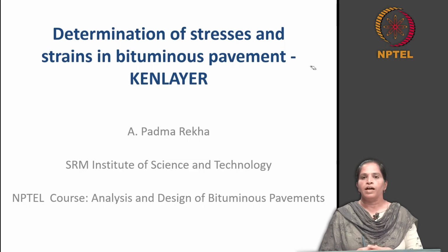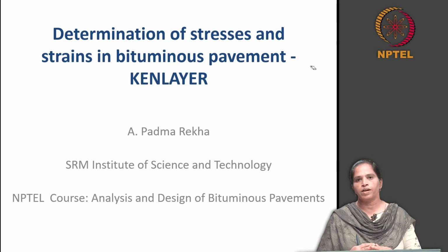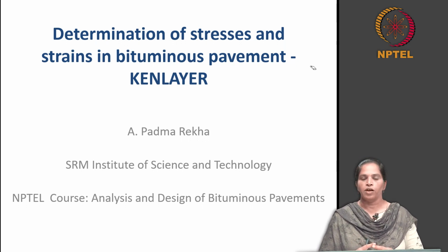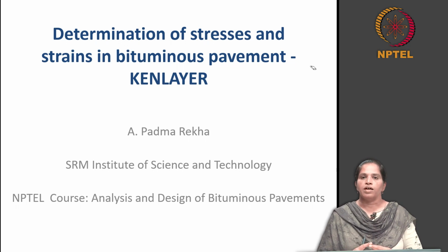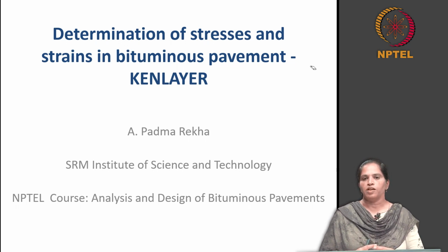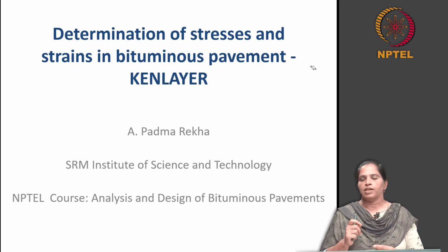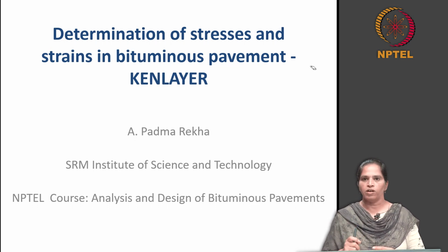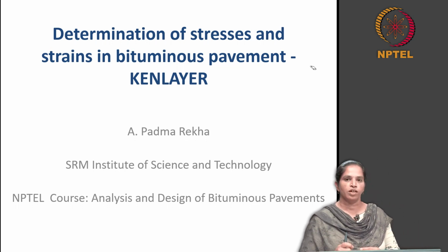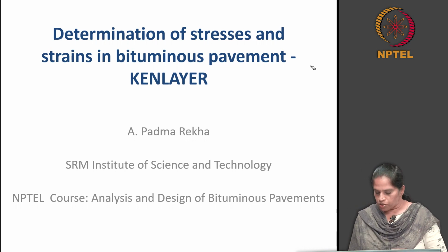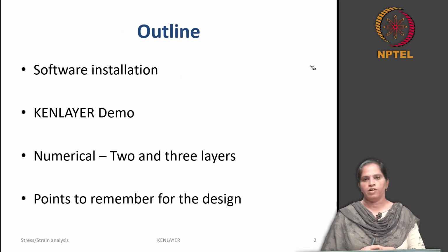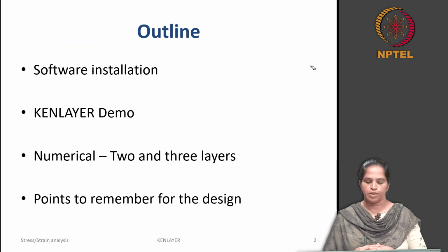Hello everybody. In this course, so far you have learned how to determine stresses and strain in the bituminous pavement using design charts. Now, we will do the same thing using a software called Kenpave. In the Kenpave software, there is a module called Kenlayer. This Kenlayer is used for determining stresses and strain in the bituminous pavement. So we will see how to use Kenlayer for the analysis purpose.